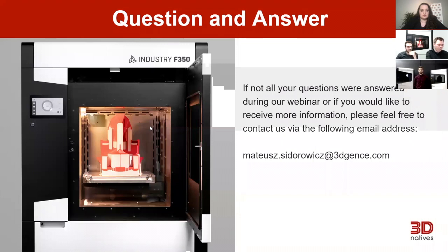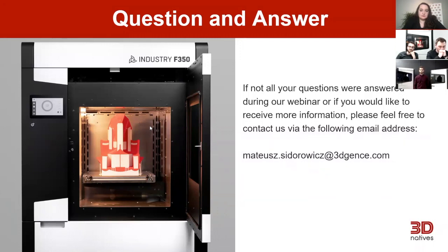A glass fiber loaded material will be abrasive because of the fibers inside, but it also will be significantly more rigid. It will display a higher tensile strength. It will be less flexible. It will be able to withstand higher working temperatures and higher loads. But it actually depends on the application again. PA6 glass fiber reinforced is actually very widely adopted in the industry.